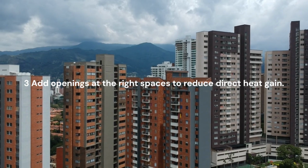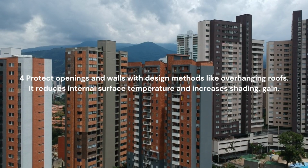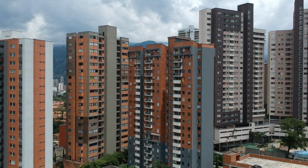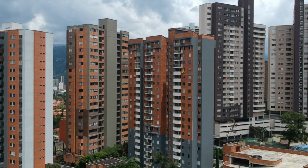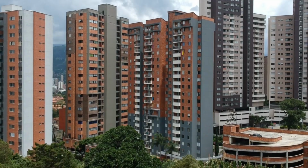3. Add openings at the right spaces to reduce direct heat gain. 4. Protect openings and walls with design methods like overhanging roofs. It reduces internal surface temperature and increases shading. 5. Consider high-mass construction for better insulation.